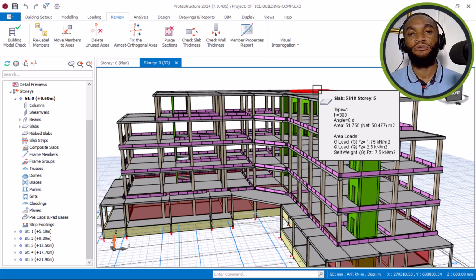So it is advisable to make sure that before you apply wind load, your building is at least 10 meters and above. And what does it mean? A three-story building with 3.3 meters headroom is not advisable to have wind load. Basically, wind load application for buildings actually starts from 4 stories, because from 4 stories you are almost reaching about 11 to 12 meters height. That's the minimum you can have.